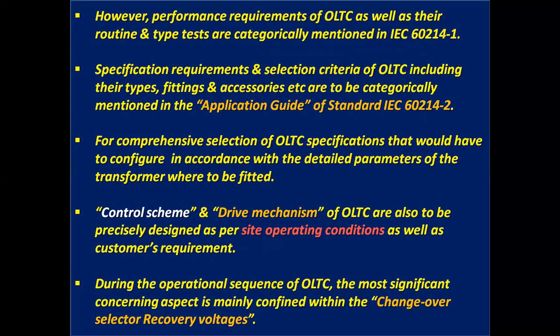Specification, requirements and selection criteria of OLTC, including their types, fittings and accessories, etc., are categorically mentioned in the application guide of standard IEC 60214-2, for comprehensive selection of OLTC specifications that would have to be configured in accordance with the detailed parameters of the transformer where they are to be fitted.